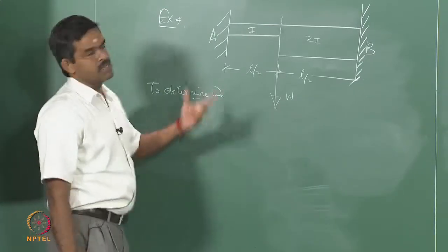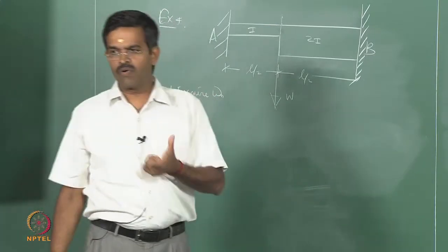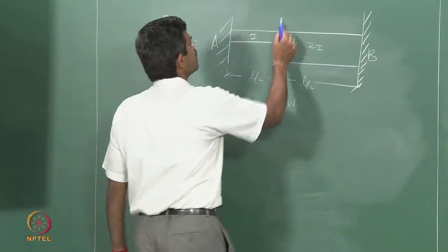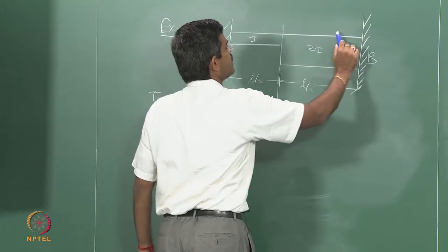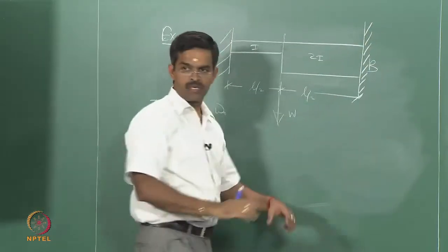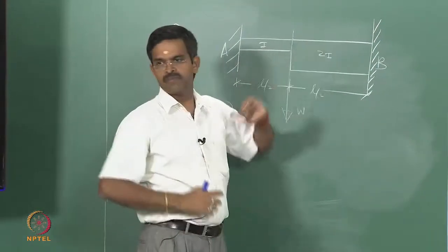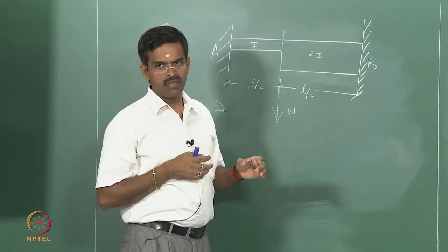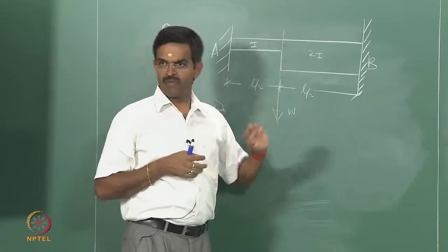It is a very classical example in the top deck system of offshore structures, because wherever you have top side crane facility, derricks, flare booms etc. located, obviously there will be deeper beams. So, you can encounter a support system where the moment of inertia of the cross section may vary.